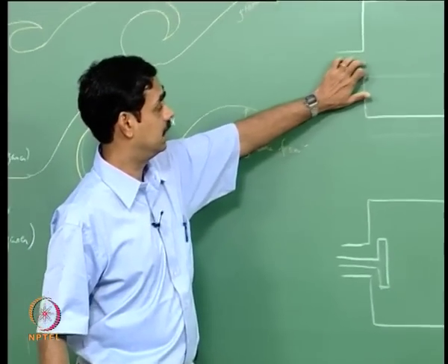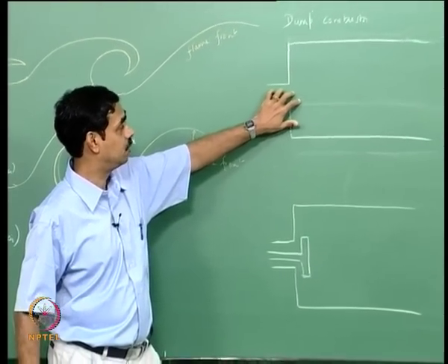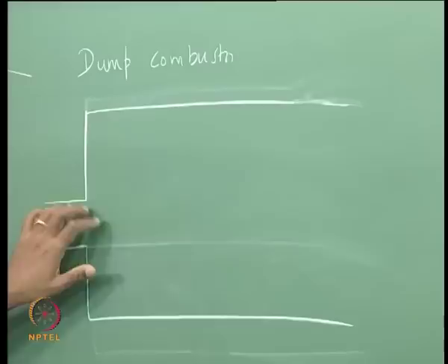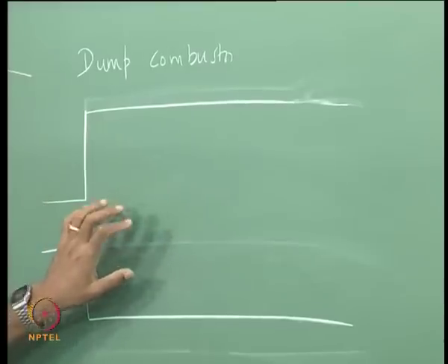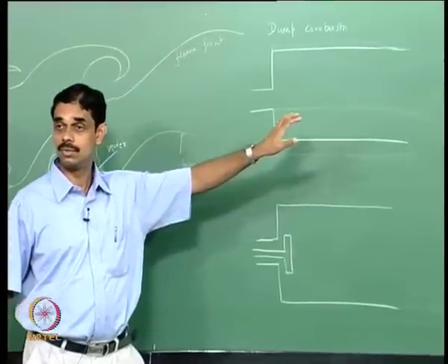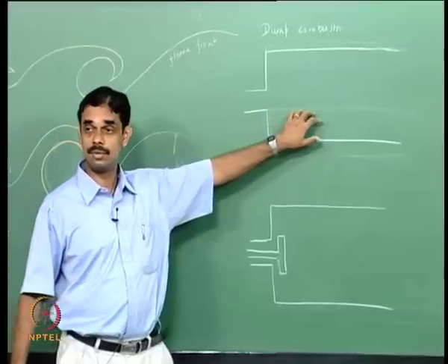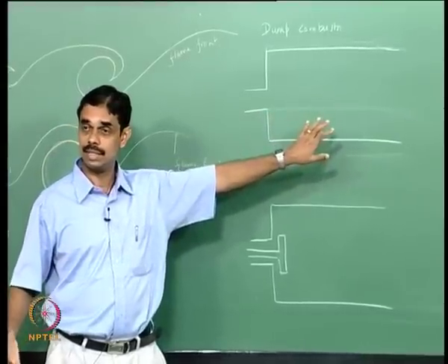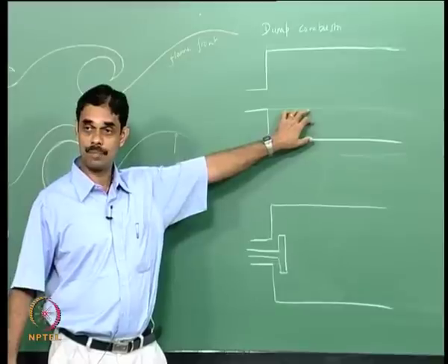Same kind of thing happens here. Here you can't tune at a given velocity, but at certain velocities the vortex shedding frequency may come close to the frequency of the combustor, and then both will lock to each other.